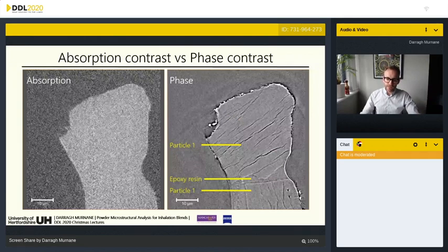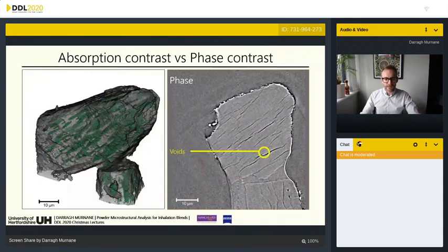And of course, this isn't just a 2D technique. We can look in 3D, and we're able to see that all of these voids seem to, somewhat interestingly, align along the same plane within that lactose. So this raises the question as to what these fringes really are and how they might impact on the particle itself. And that's something that we're looking at in closer detail with the material suppliers to try and understand whether it's a process-induced disorder. We don't think that it's related to the analytical technique itself, because we produce control crystalline lactoses that don't exhibit this behavior.